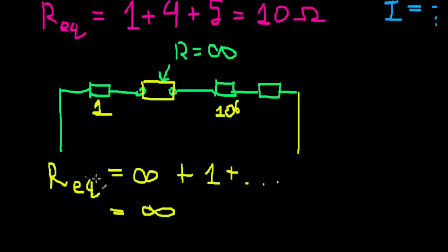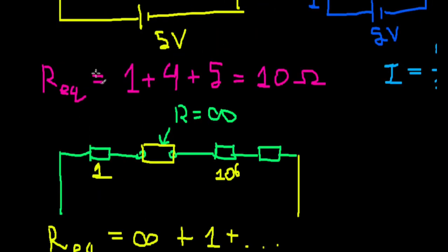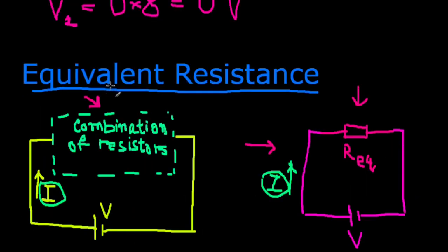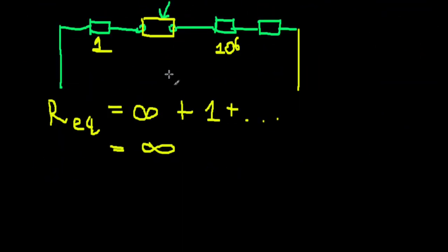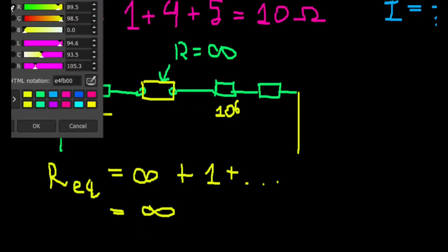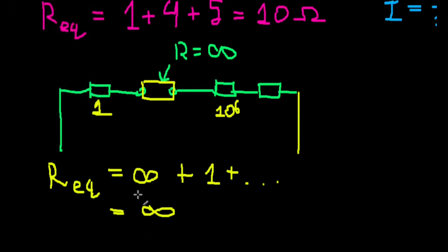So that's why, for any reason, when you have an open circuit in a series combination, your resistance becomes infinity. That also explains why no current would flow through. The whole series combination stops receiving any current, because due to the open circuit, it has an infinite resistance. All right, so I think that's enough discussion for series circuit.